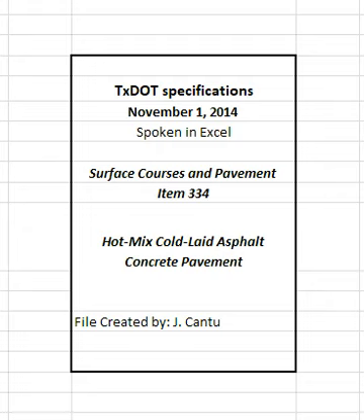4.1 Mixture Design. 4.1.1 Design Requirements. Use the typical weight design example given in Tex-204-F, Part I to design a paving mixture that consists of a uniform mixture of aggregate, asphalt material, primer, additives, and water, if allowed, which meets the requirements shown in Tables 4 and 5, unless otherwise shown on the plans.